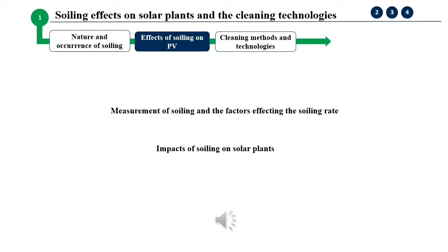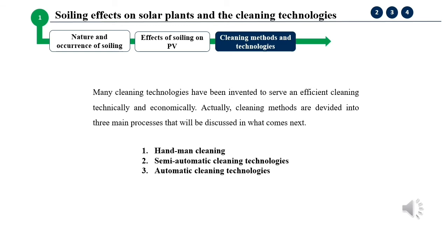On the other hand, soil deposition on PV panels serves as a thermal barrier against the sun's insolation, which leads them to be cooled by several degrees. This cooling may increase the open circuit voltage, but it decreases the short circuit current. The panel's surface cleanliness is related to soiling rates, which depend on weather data: wind speed, relative humidity, and wind direction. Research shows that the faster the wind is, the cleaner the surface is, especially for dry dust, but a high relative humidity level causes particles to stick on the panels and be hardly removed by wind only, which makes soiling more severe on the surface.